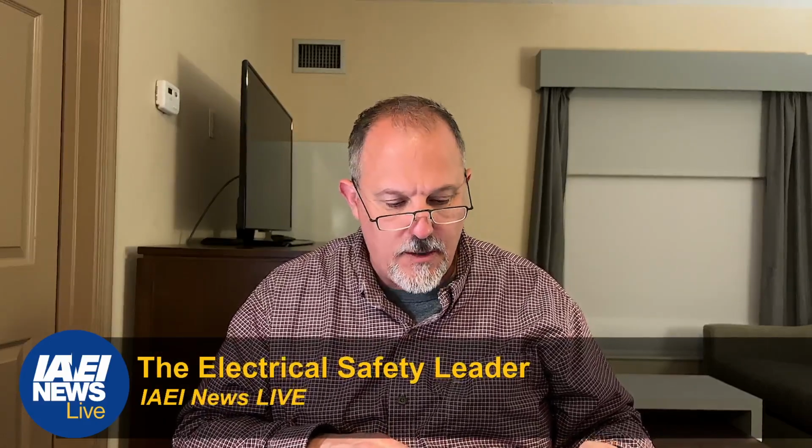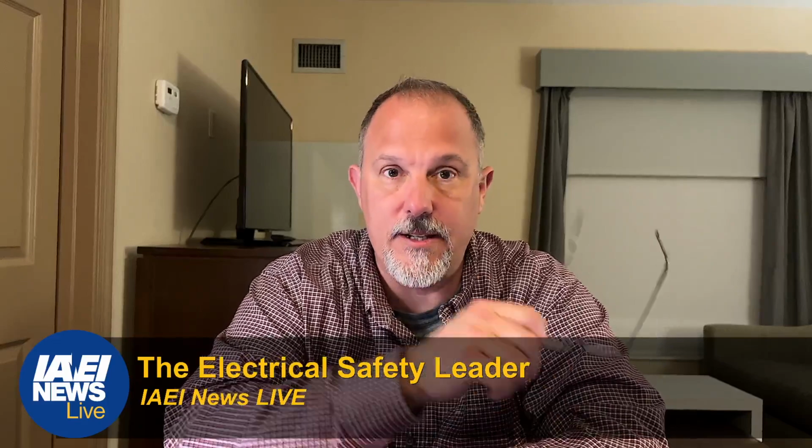So 210.8(A), exception number 1, that doesn't help me, because exception number 1 covers receptacles that are not readily accessible and for GFPE equipment. So, yeah, I think that's a little problematic. We've got some love to give to 210.8(F).